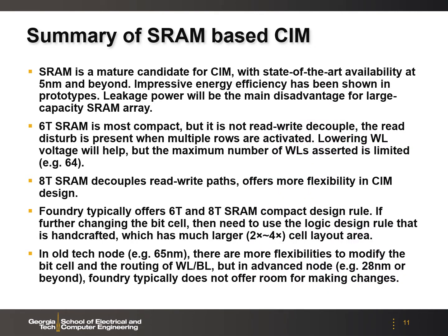SRAM is a mature candidate for computing memory with state-of-the-art availability at 5 nanometer or beyond. Impressive energy efficiency has been reported, but the leakage power will be the main disadvantage for large capacity SRAM arrays, as SRAM is always leaking even in the standby mode.